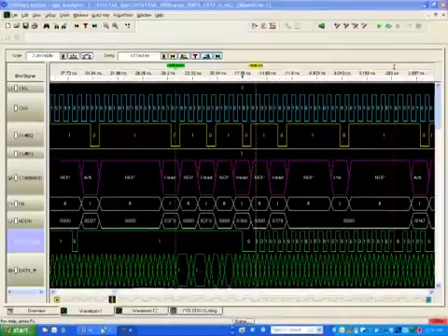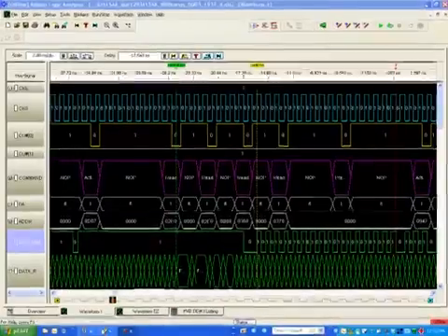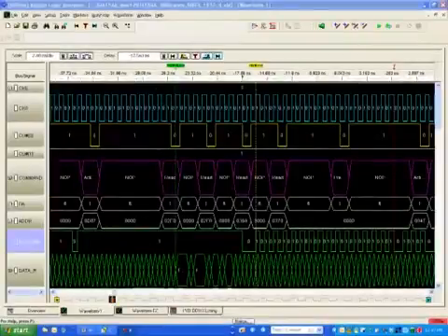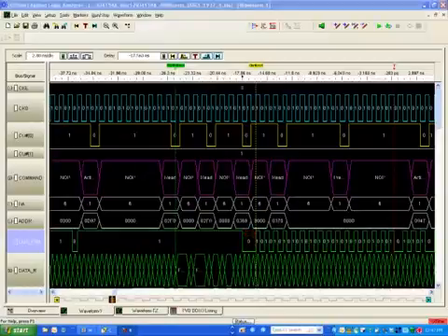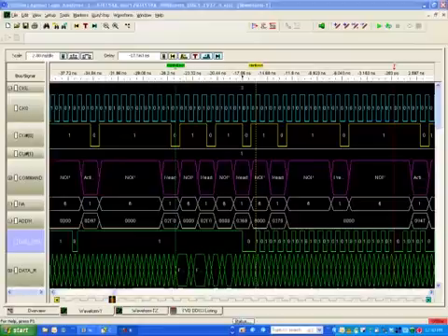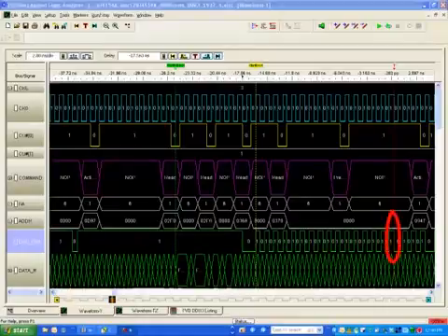Opening the state waveform, on the left we see an activate, then 4 valid read requests back to back. On the DQS line, we can see the preamble followed by the 4 back-to-back bursts of data, and we can measure the CAS latency between the first valid read request and the beginning of the data strobes. Notice that the logic analyzer triggered at the end of the 4th burst.